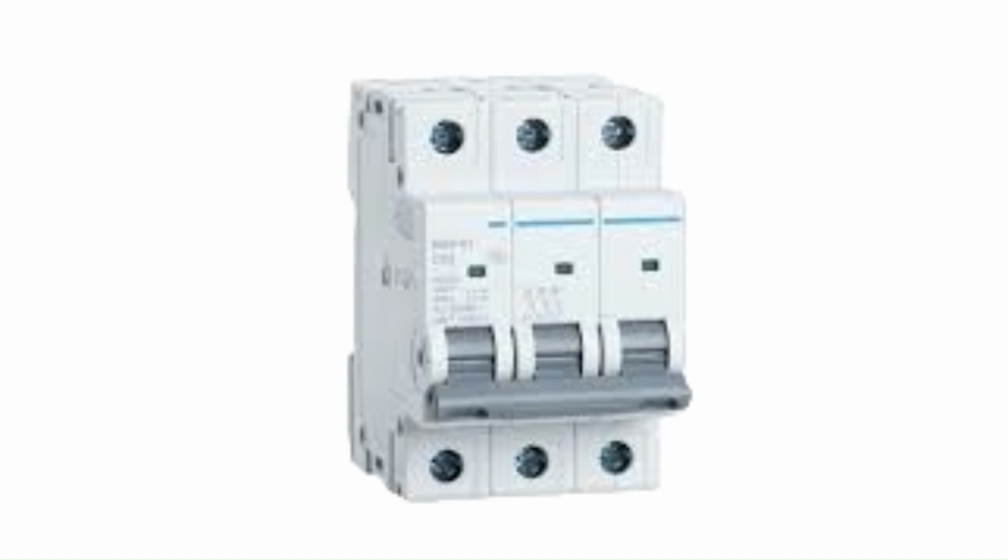MCB is an automatic switch that opens when excessive current flows through the circuit. It can be reclosed without any manual replacement, unlike the fuse, which must be replaced or rewired once it breaks. This is the main reason why MCBs are used as an alternative to the fuse in most of the circuits. Handling MCB is relatively safe and it quickly restores the supply. It can be reset quickly and does not demand more maintenance. MCBs have ratings under 100 amperes.